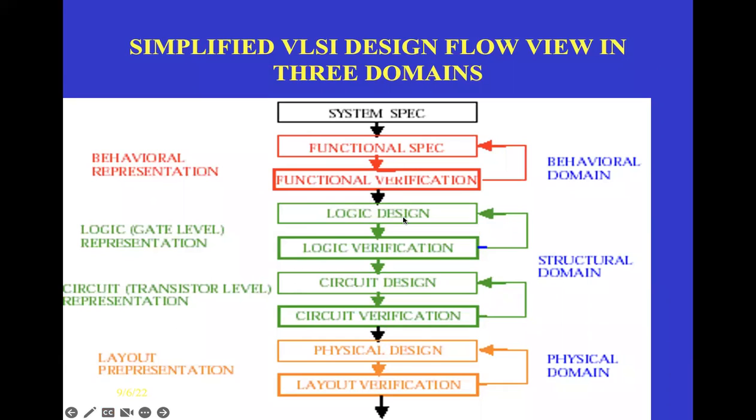So moving on, you have logical design. Whatever you design, you need to verify it. Once you're fine with that, you can put it in the form of a circuit, and you verify the circuit. You have a physical design for that. Again, in physical design there are a lot of checks that happen: DRC, LVS, parasitic extraction, back annotation, many things. And that's where verification happens.